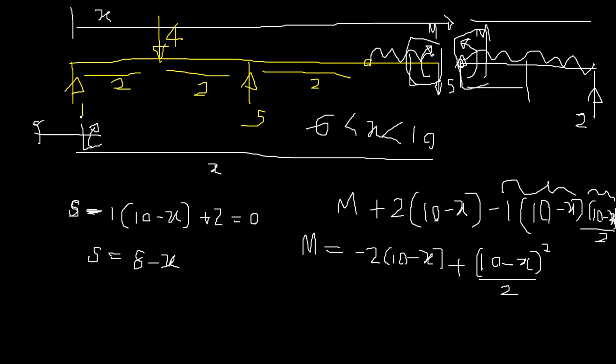Since we usually cut from the right and take the right end, that's why we consider clockwise positive. But here you are taking anti-clockwise, so take anti-clockwise positive. At the end, it is going to be a hogging moment, and that's what matters, not anti-clockwise or clockwise. To be a hogging moment, if it is the right end, that's clockwise. If it is the left end, it is anti-clockwise.